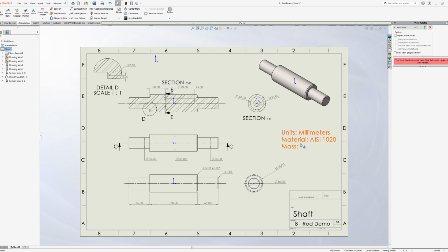It does take a little bit of finesse sometimes. Sometimes creating some measurements might be trickier than others. Try to look at whatever error it might be giving you if it does. So if you try to smart dimension two things, generally speaking, if it can't create that smart dimension, it will say something. It will give some sort of details regarding, hey, there's a specific reason that this isn't working here.